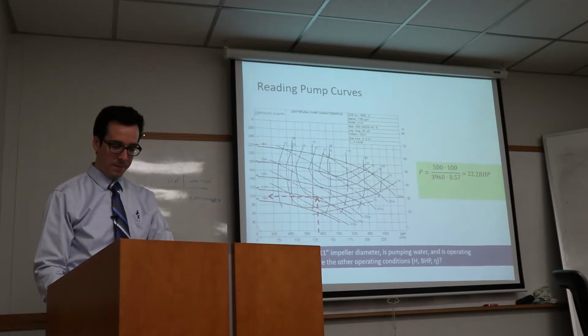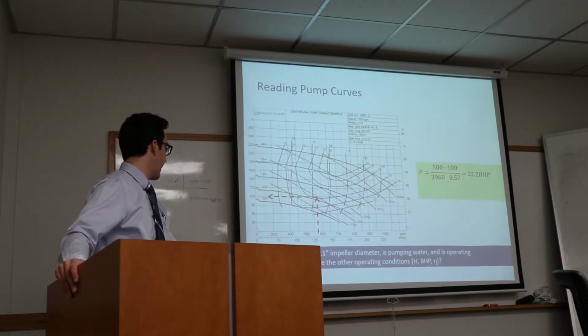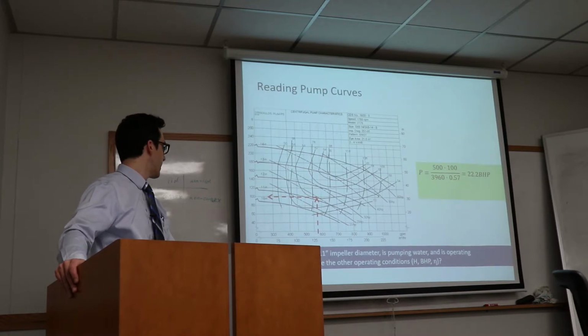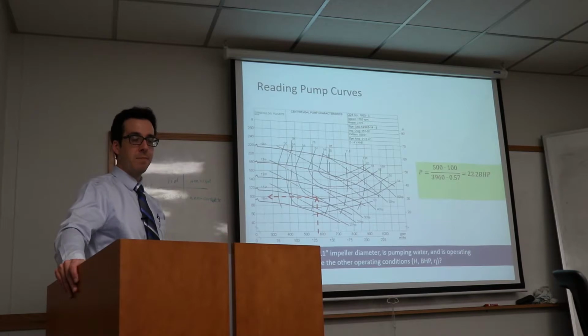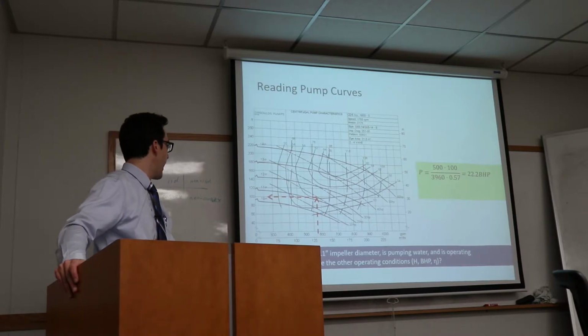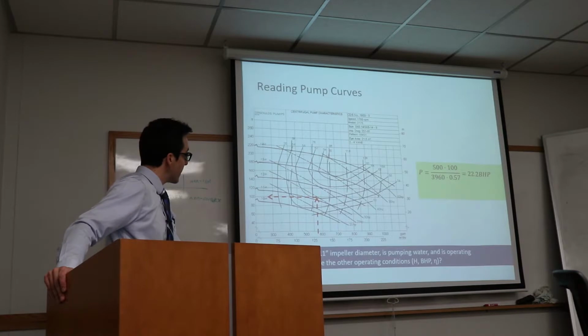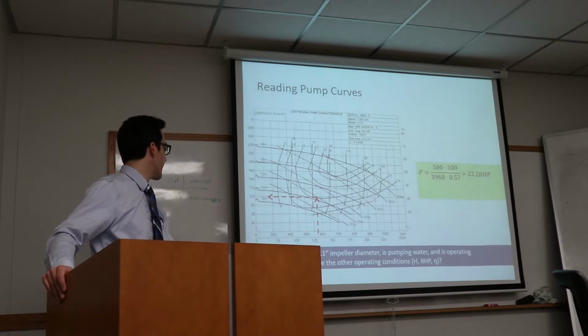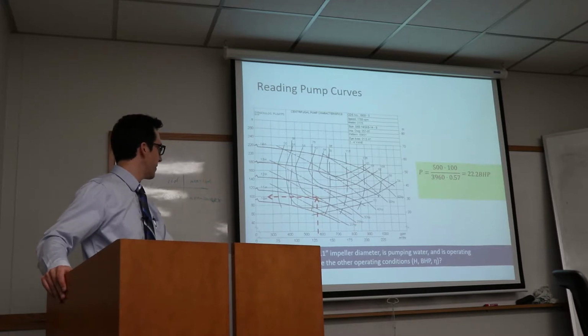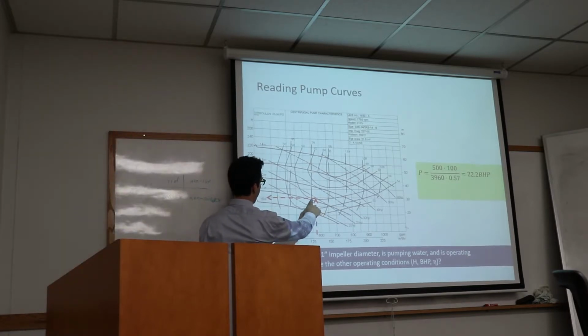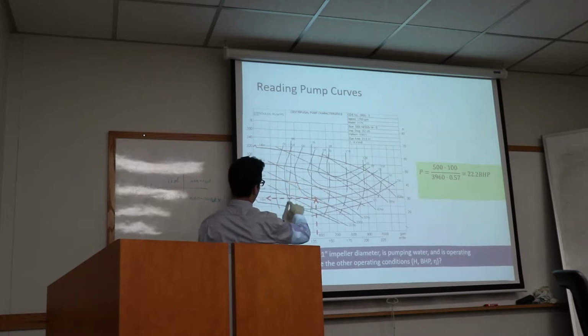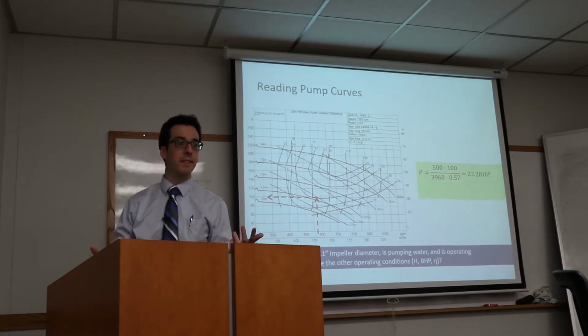So there we are. What is the operating head? Yeah, it's 100 feet. So we have 500 GPM, we have 100 feet of head, and reading in between the efficiency curves, where do you think that lines up? I know my vertical arrow is a little bit shifted, but... Is it like 52? I can't really see that. Yeah, so we're looking about right here. It's somewhere between 54 and 58. So we'll call it 57, okay?